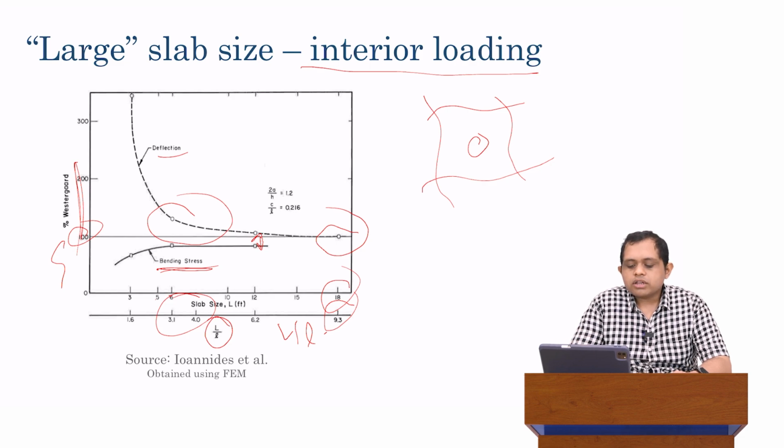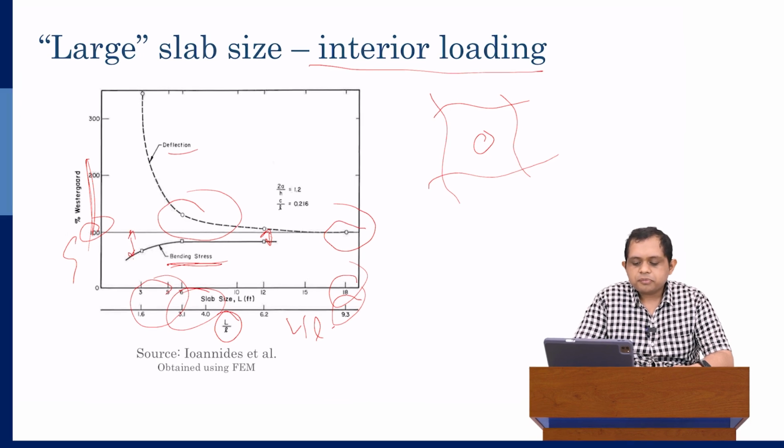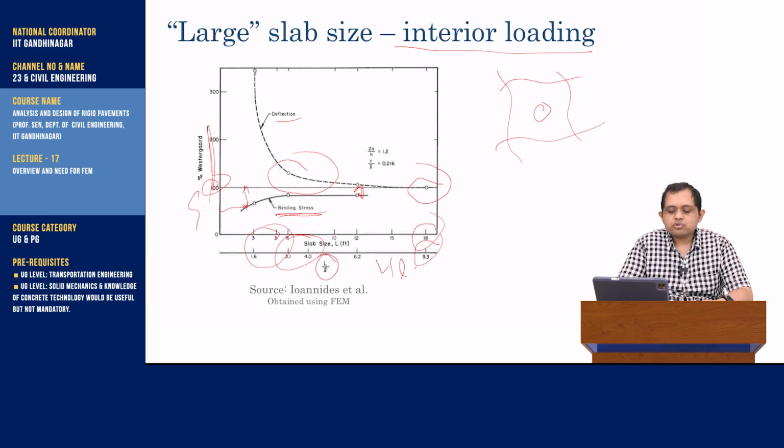Now, on the other hand, when we go to relatively smaller slabs, so we go down to this range of maybe 1.1 to 2 in the L over L ratio, we see that that difference is just getting larger. So over here, for example, just roughly speaking, perhaps the analytical solution is 50% of Westergaard's solution. So Westergaard's solution is, roughly speaking, estimating a value of bending stress which is double the value which we're getting for numerical solutions when we look at smaller slabs.